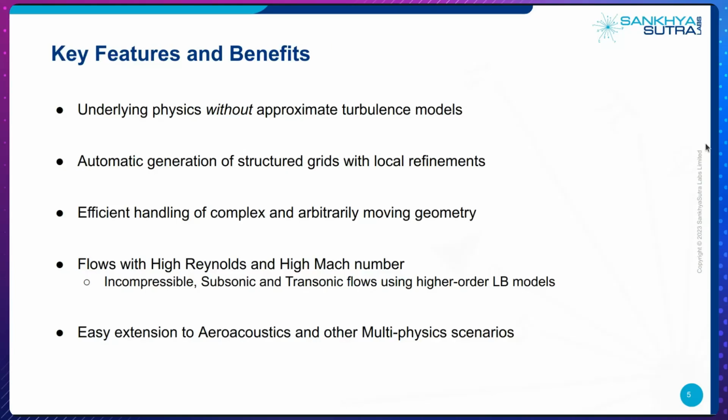So the key benefits, I would say, of using SankhyaSutra Taral are that you are actually solving for the underlying physics without the use of turbulence models to approximate the behavior of the flow. What I mean by underlying physics is the solution of the Boltzmann equation and not an approximate solution of the Navier-Stokes equation.